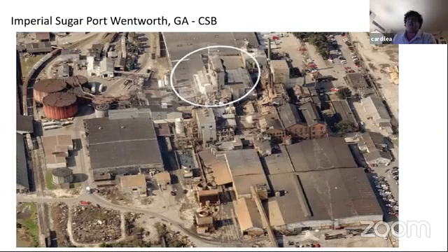In one, they just lit it on fire in a metal container that was open, and you just see a little fireball flash up, not too big of a deal. That's what typically happens in a dust explosion. In the second scenario, they close the lid and latch it shut. Because you have the expansion, it happens so quickly with that burning, it shot the lid off and shoots it about 30 feet into the air, which goes to show you it doesn't take very much to have a lot of force generated from one of these explosions.